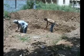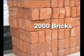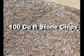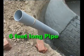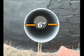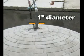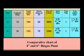For the construction of a 4 cubic meter capacity biogas plant, the materials required are 2000 bricks, 18 bags of cement, 100 cubic feet stone chips, 100 cubic feet sand, a 6 feet long pipe having 6-inch diameter, and a 1.5 feet gas outlet pipe of 1-inch diameter. Similarly, for constructing a 6 cubic meter biogas plant, we require some extra material as shown in the table.